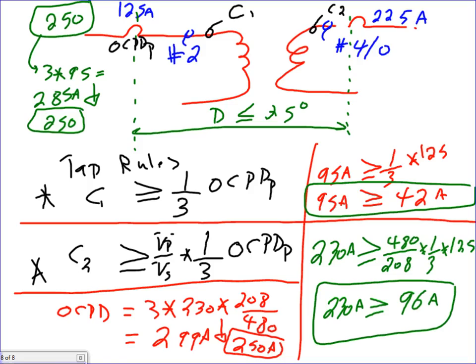Yep. FYI, guys, in 2011, right now, the NEC code said that you have to have a disconnect right next to the transformer or identified if it's farther away. So this circuit breaker right here most likely is going to be very close to the transformer, within sight. They say within sight though. Or it has to be locked in the open position if it's not within sight and identified at the transformer. Any question, guys? This is one rule of the transformer rules. There's a few other rules I'll be going over as we go through. I'm sorry it's monkeying around with numbers, but it allows you to design different than what the code says in the book, based on the tap rules.